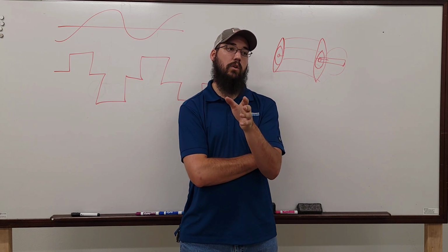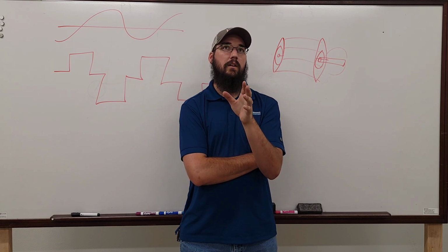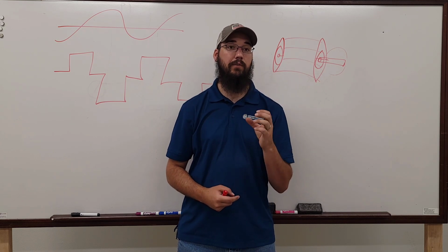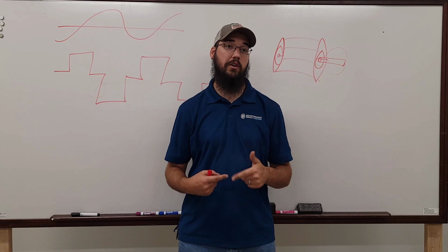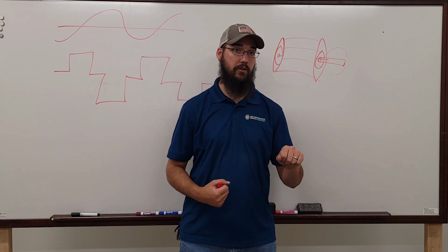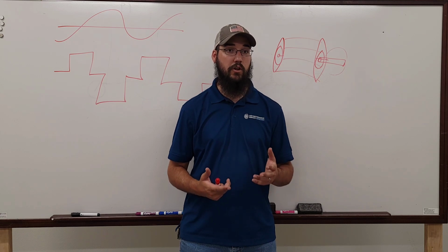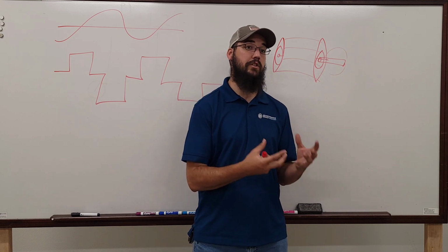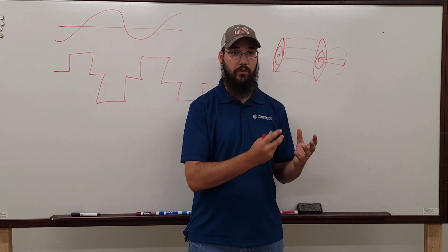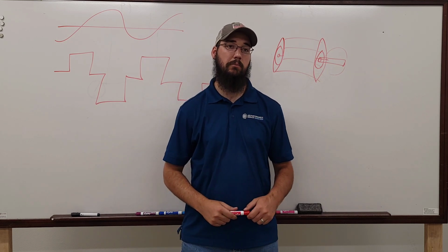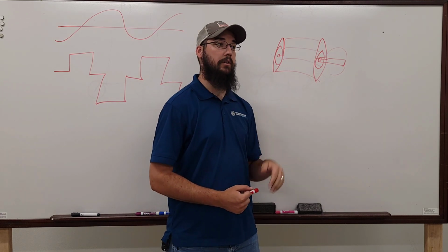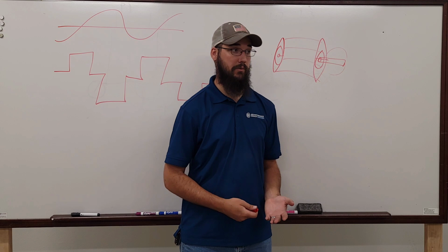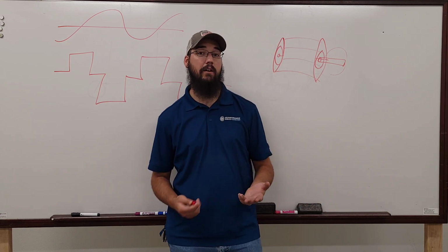Inevitably, though, what we're accomplishing is the bearings, because they roll and there's grease, don't always make perfect contact. So a literal charge is able to build and then discharge. With shaft grounding, the charge is never even there. So whatever electrons would be generated or induced, they're always getting passed on back to ground. This is extremely important, and this is a difficult conversation we're having to have with a lot of customers. And we have documentation, we have articles.